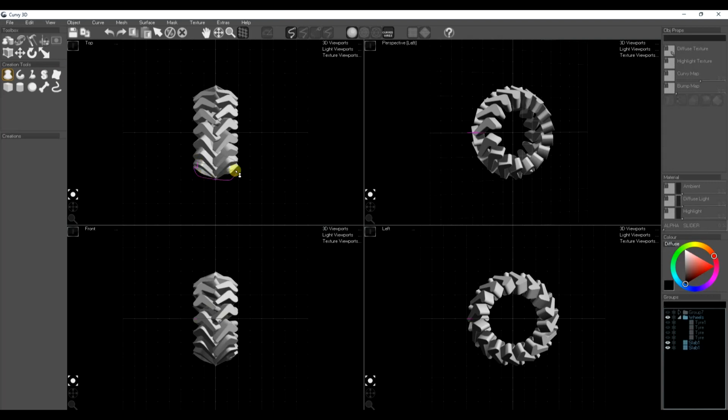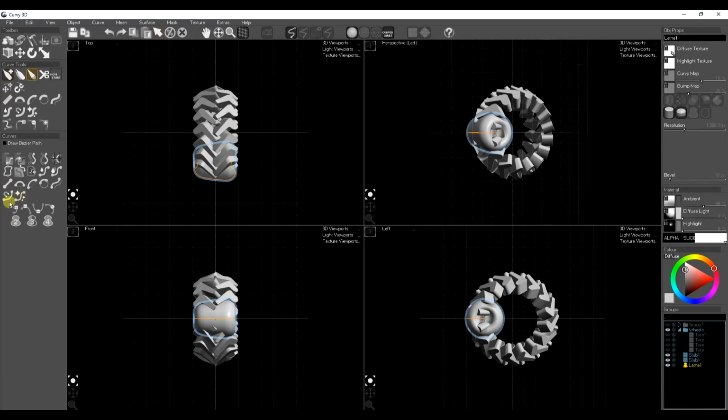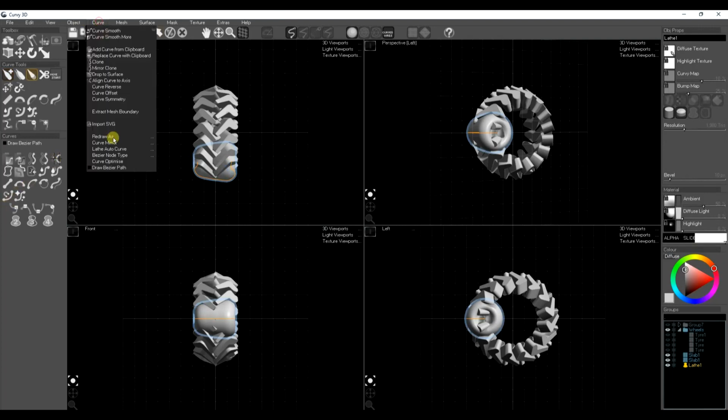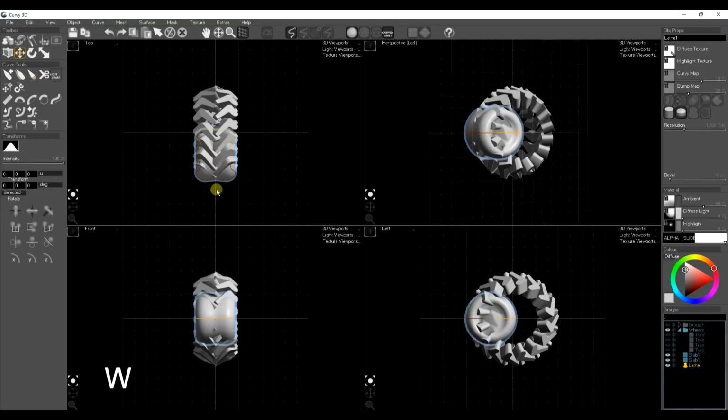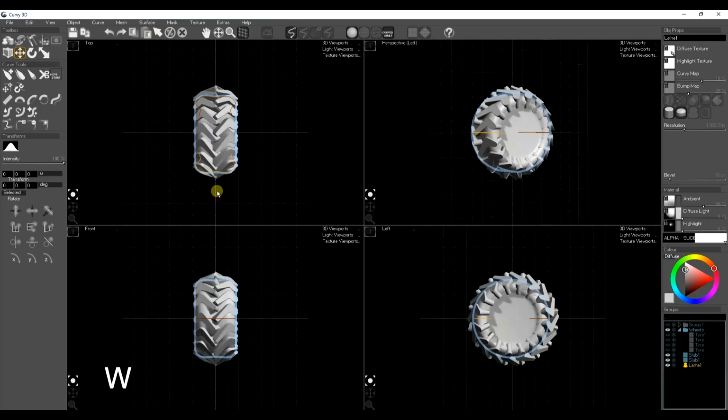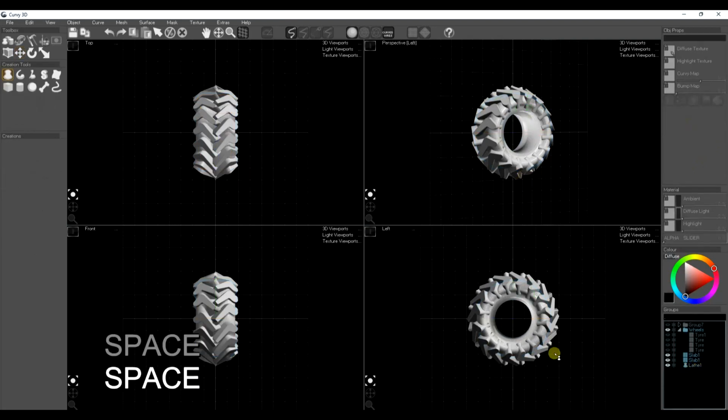Lastly, I'm going to do the body of the tyre as a lathe object, which is sort of a wide U shape, and use the curved mirror to make that symmetrical and turn that into a 2 curve lathe and move the ends into place. I want the center to be hollow as well, so I'm going to turn off cap ends and turn on the loop, which will fill in the inside of the wheel. And that's one tyre done.